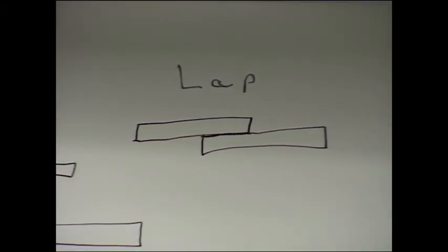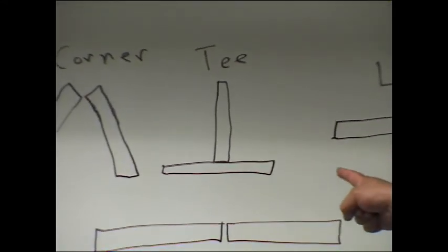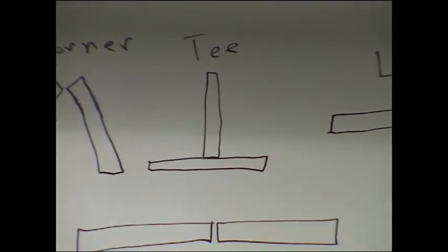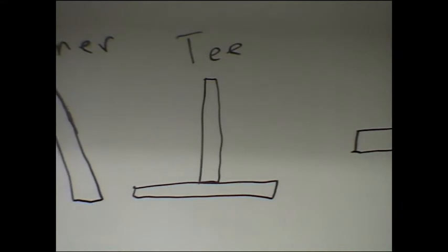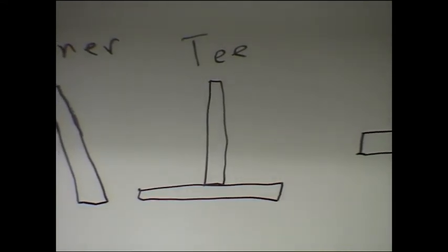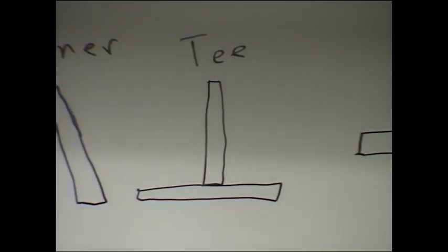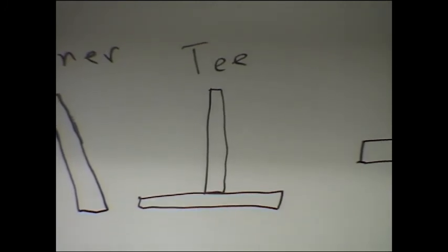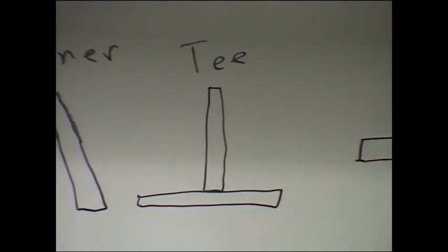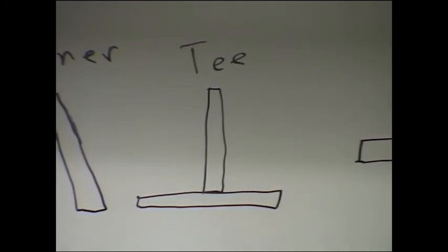Welding a T-joint, that's also a fillet weld style right there. And with oxy-acetylene, you can weld one side, but it's really hard to weld both sides. What happens is you get so much metal built up on one side that you almost can't generate enough heat on the other side to get it to melt properly. So you'll just do one side of that one.